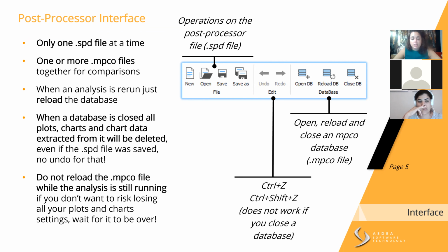You can also use the undo and redo buttons, but remember that if you close or unlink your database, those buttons cannot be pushed anymore. So if you erase the database from the SPD file, you cannot go back and just load it again. So unloading is final. And of course, you can open and close the database, but remember, you can also reload it. So if you rerun your analysis and you just want to reload the database in the same SPD file, you can just click on the reload button. I suggest you not to do it as OpenSees is running, because you can open a database as OpenSees is running for the first time, but the reload button doesn't always work if you are rerunning your analysis.